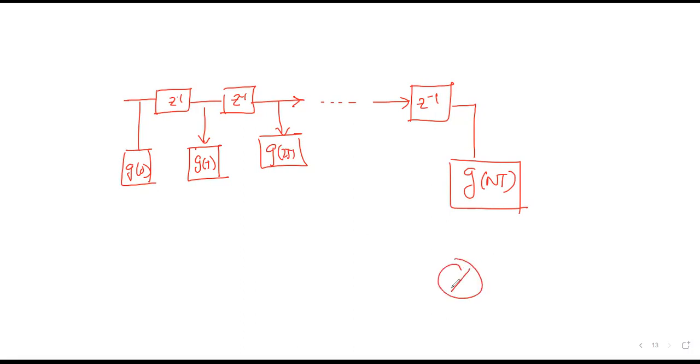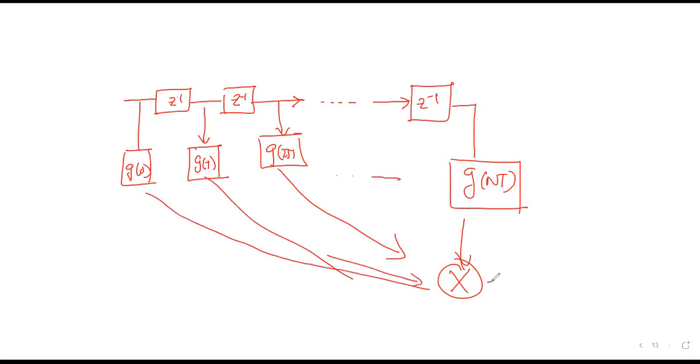All these will be summed together to give you your final value Y(z) or y(k). So this is your x(k) or X(z). This is the block diagram realization of a non-recursive or moving average filter with n intermediate terms. You can have a look at the summary of this implementation, which will give you an even better picture.